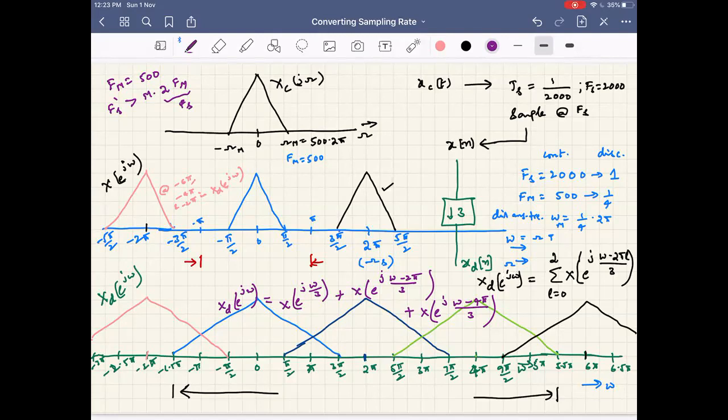But if I know that I will be downsampling by M times, that is, initially sample with Fs and downsample by M times, then Fs dash to avoid aliasing has to be greater than M times Fs. That is not satisfied in this situation.